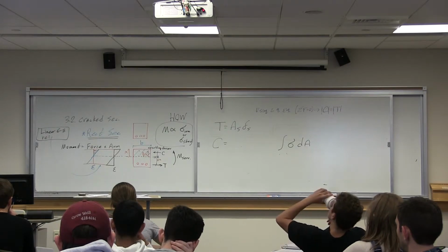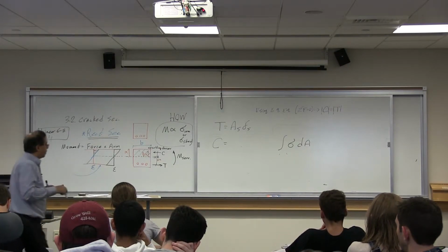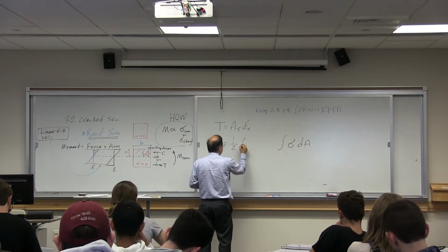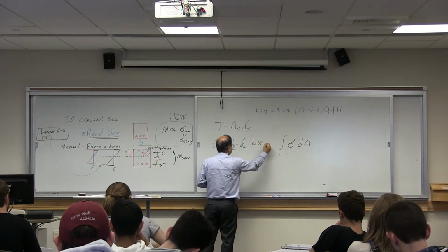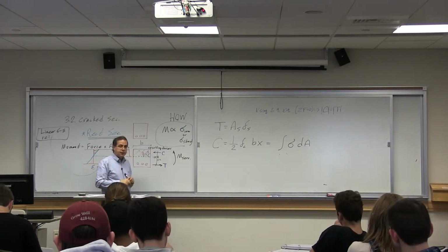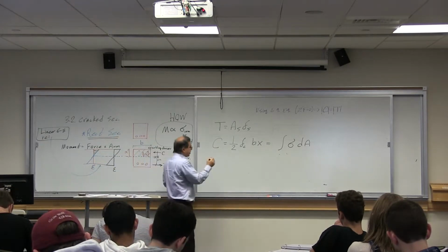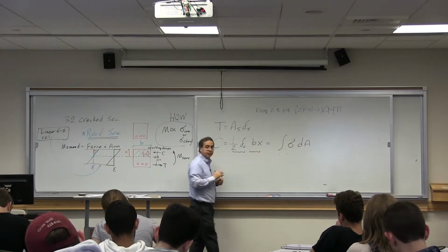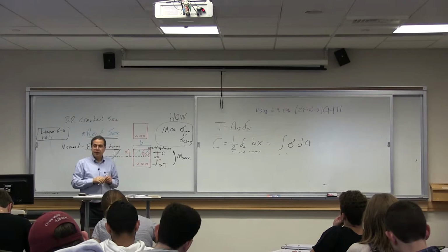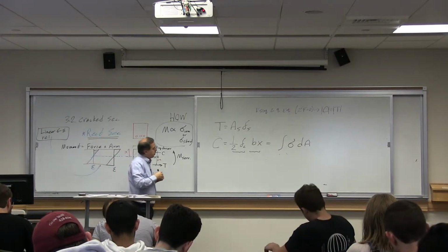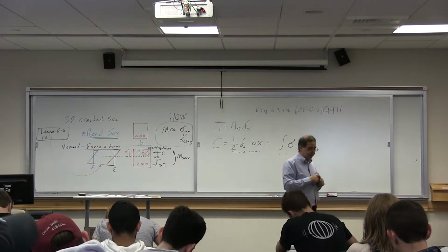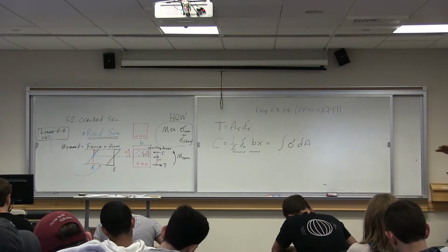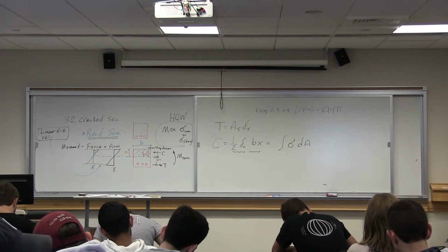Because it's varying linearly, if you integrate it, as perhaps you have seen before, it is going to be 1/2 of Fc times B times X. This is the average stress for a linear variation, and this is the area. So the compressive force is 1/2 of Fc B X. B is how wide the section is, X is how deep the compressive zone is, and 1/2 because the stress is varying linearly.